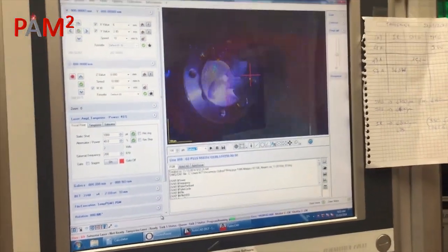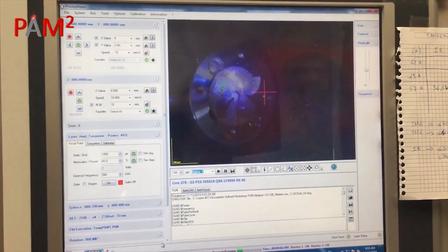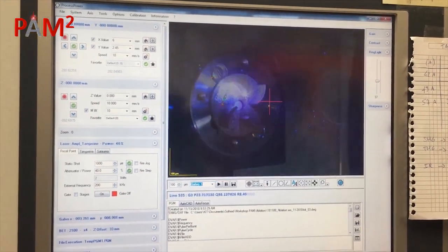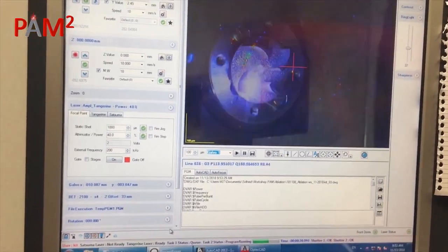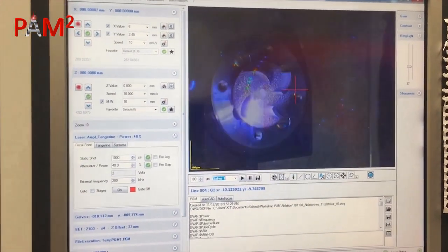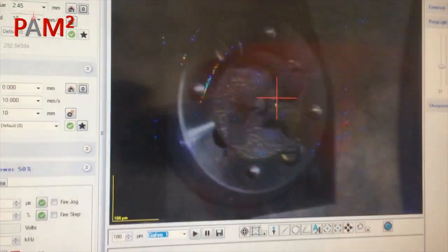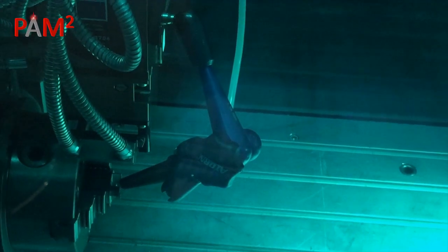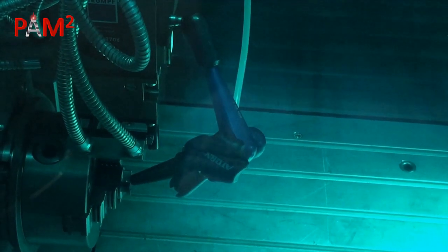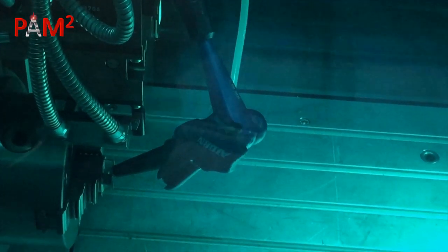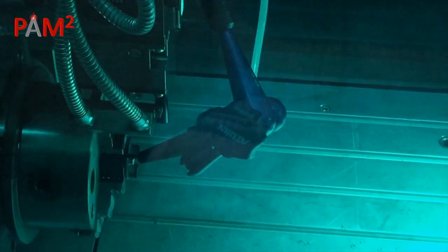It is a rapid laser post-processing technique based on the principle of remelting the material surface of the component with a laser. Continuous or pulsed laser beams with high energy levels are used to irradiate the material surface. The interaction between the laser beam and the material surface leads to partial evaporation or remelting of the material. As a result, due to the combined effect of surface tension and gravity, the melt pool is redistributed to a horizontal level, which reduces the surface roughness.